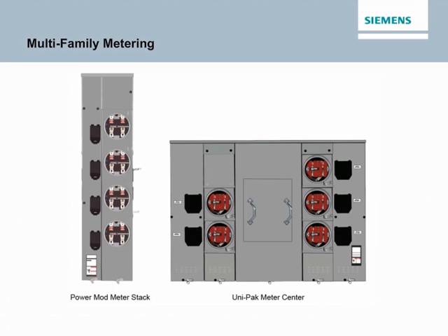PowerMod with Quick System Modular Metering is used for multifamily dwellings or other commercial applications where more than 6 meters are required. As the name indicates, PowerMod incorporates modules that can be quickly combined to meet varied application requirements. Basic modules include circuit breaker mains, fusible switch mains, top boxes, and residential and commercial meter stacks.